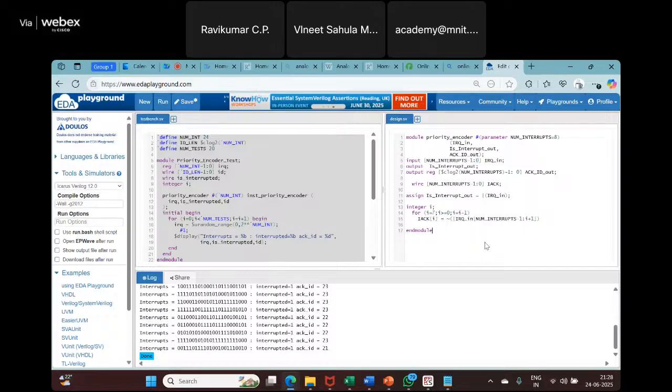Anybody higher than me is not interrupting. Then this NOT will give me a 1, right? Then I can AND it with IRQ of I. So I believe this is how we generate the IAC. This should not be 7. It should be num interrupts minus 1.